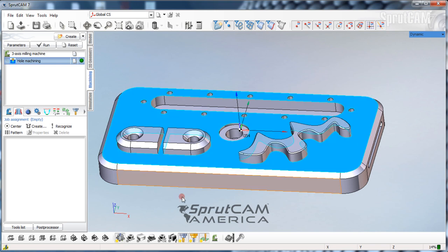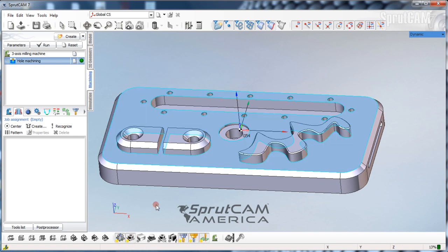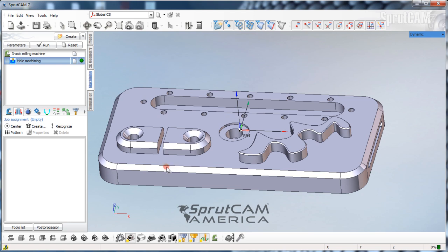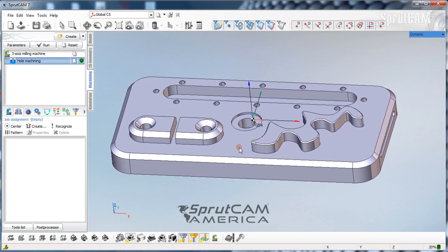There is a chance if you put something like the Part Visibility button on and turn off Geometry Model Visibility, you will not be able to touch anything and you'll think, well, here's my part, everything looks fine, but that is the issue.